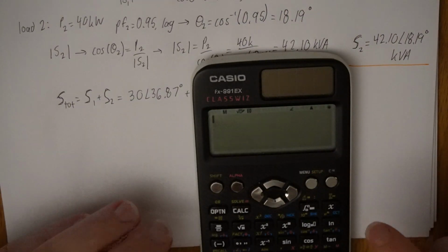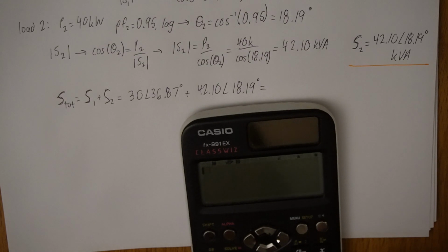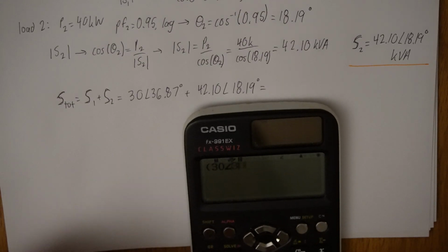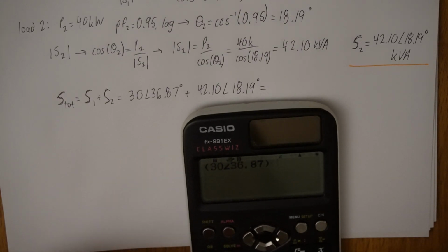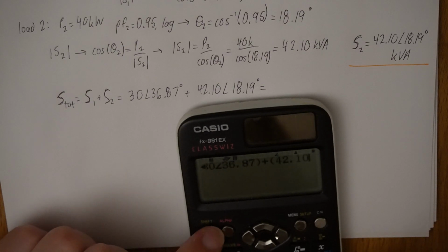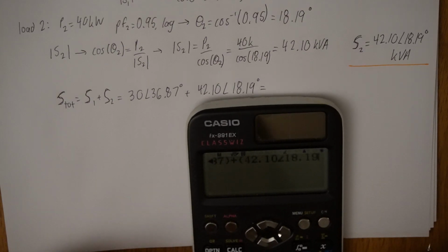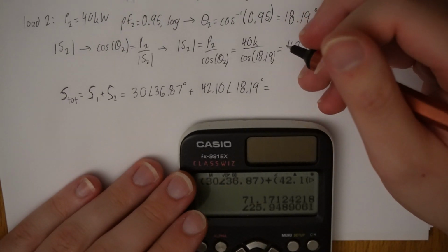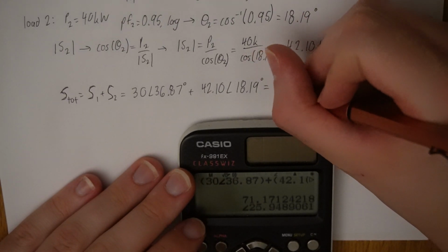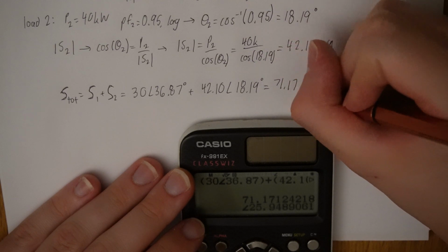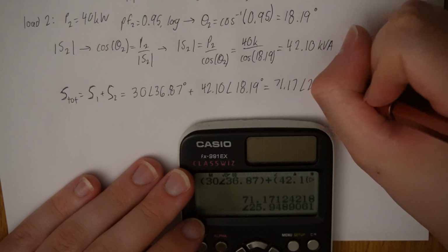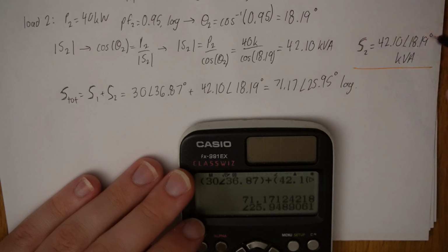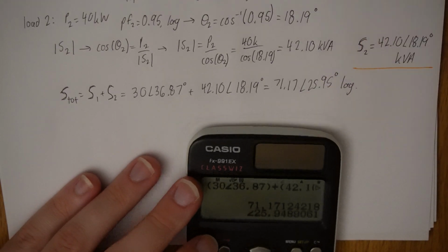I'll just do this in my calculator. Equals 71.17 angle 25.95 degrees. Lagging because it's positive, that's fine.